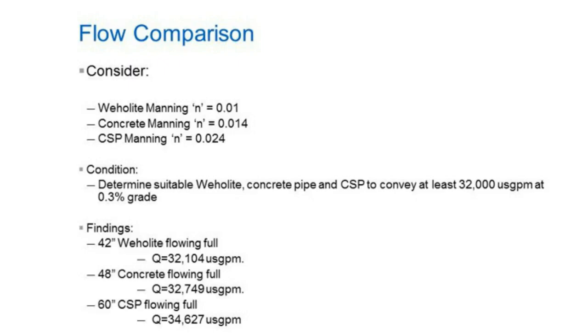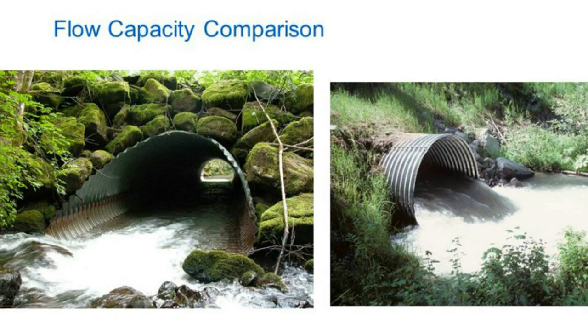In a culvert situation, we know that flow is governed by inlet and outlet geometry, so it may also be necessary to consider loss of cross-sectional area when reducing the inlet and outlet of the pipe with relined pipe. In many cases, the existing culverts have been over-designed and the reduction may not matter. In other cases, it may be critical to not have backwater conditions that exceed the existing conditions. Although we are reducing the diameter, the reduced Mannings n can allow the water to move better through the culvert and thus help to reduce this backwater situation that may occur.